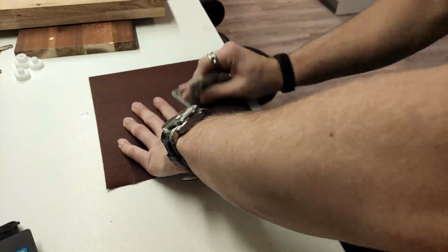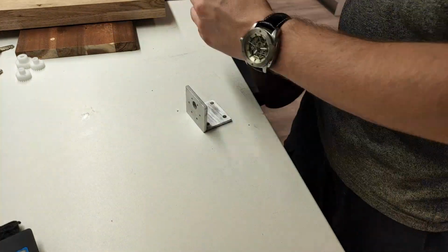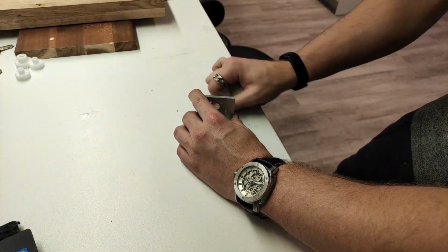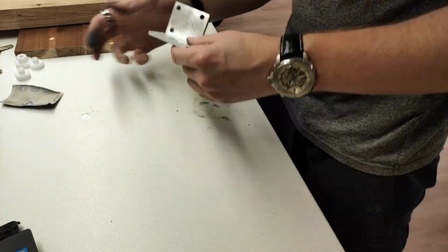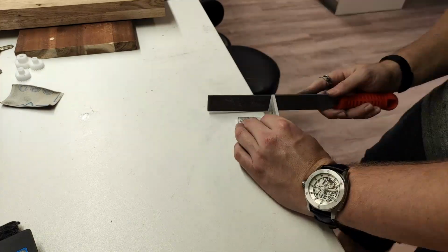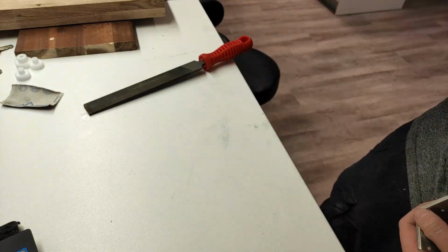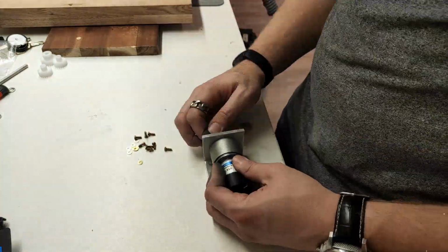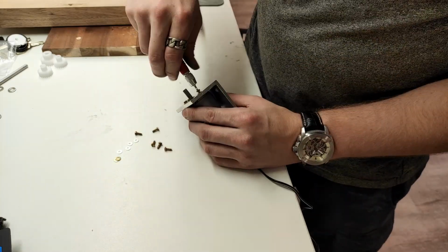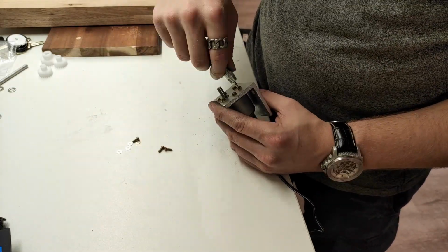Here you see me sanding down the holder for the motor that I built. I sadly lost the footage of how I built it, but basically I just cut a piece of an L-shaped aluminum profile to the desired length, and then I drilled some holes to fit the motor onto the L-shaped aluminum piece. The motor runs pretty slow with 12 revolutions per minute, and it has a torque of about 100 Newton centimeters, which I thought should be strong enough to drive all of the gears.